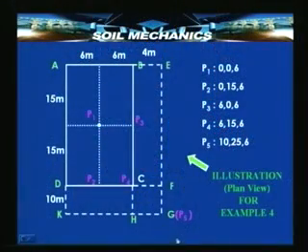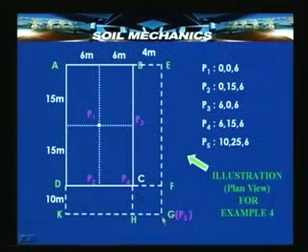But however, now if you see, CFGH figures in both these rectangles which have been additionally added. Since this is getting subtracted twice, we need to now add at once the stress due to CFGH. Since that also has G as one of its corners, the stress distribution can be computed by the same manner by taking an influence coefficient for the area CFGH. Now, let us see how this is done.